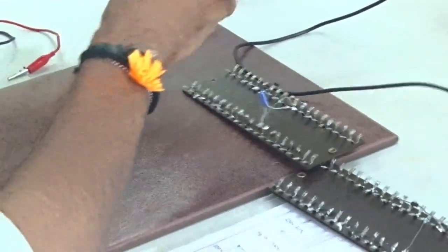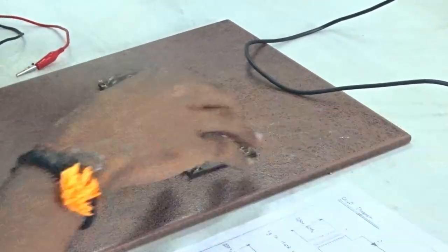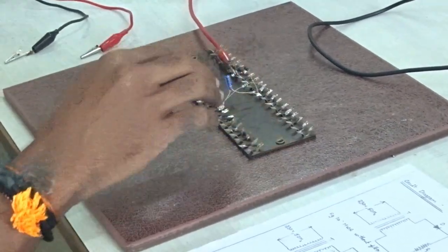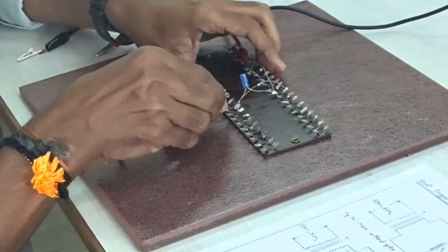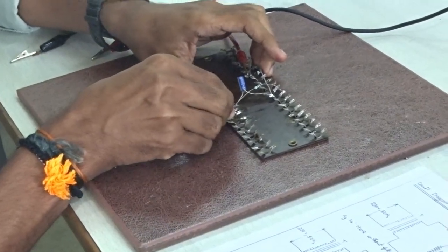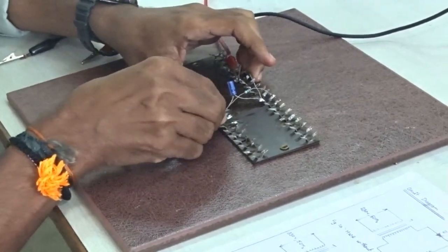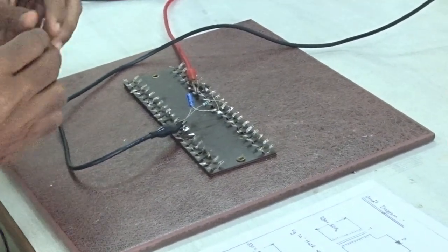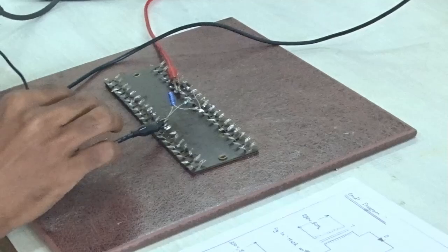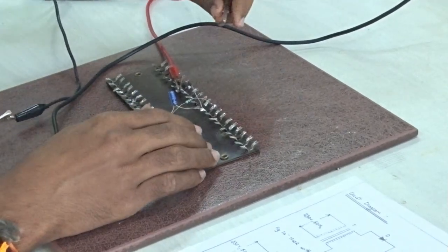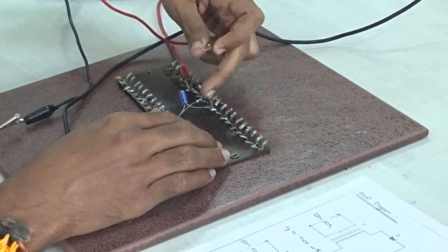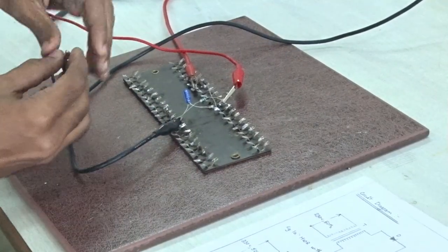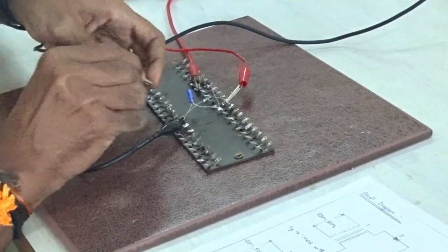That is, a 12 volt line will be connected to the anode of the diode, and the ground line will be connected to the other end of the resistor, and then the probe from the oscilloscope will be connected to the point where the cathode of the diode, resistor and the capacitor meet, and the other end of the probe will be connected to the other end of the resistor.